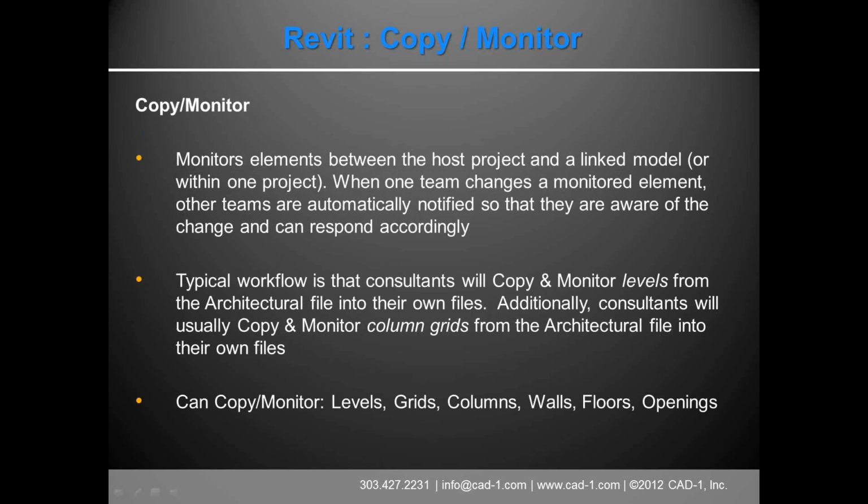So the copy monitor tool monitors elements between the host project, which is your project, your live file, and the linked model, or you can do it within your own project. And then when one team changes a monitored element, you know, moves something that you're monitoring, like say a level or a grid line, the other teams, as soon as they get that updated file, are automatically notified so that they're aware of a change and can respond to that. Because if a grid line moves or a level, a second floor, third floor, if the floor slab goes up or down, you probably want to know that.